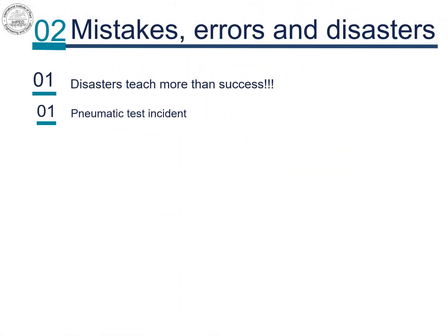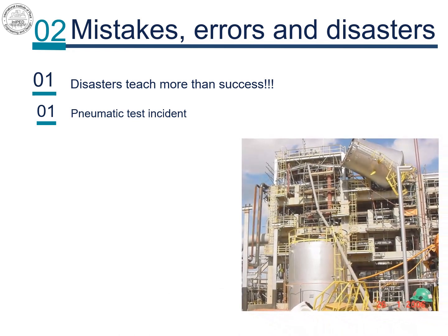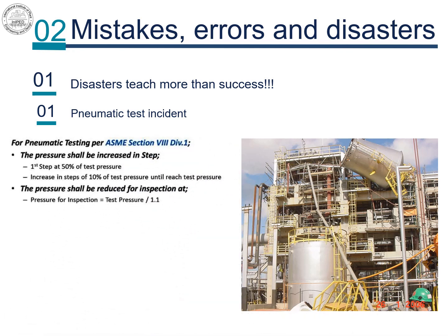The tank lifted off and was found on top of the unit. This was an amazing event, having in mind the knowledge that pneumatic testing always involves the hazard of a potential for sudden release of energy stored in compressed gas, and if we also assume that the following procedure, which specifies the basic requirements of pneumatic testing, should have been followed, as per ASME B31.3 and ASME Section 8 Division 1.